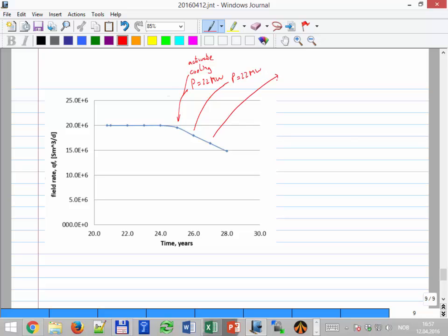And then at this point I had to reduce the rate for the temperature to be exactly equal to 150 degrees C, the temperature at the discharge. From that point it also becomes limited. The power is less than 22 megawatts, but the discharge temperature is already locked at 150. So that's why it's so important to foresee if I can make a better cooler, if the cooler can operate more efficiently to take it down closer to 6, because then I will be able to produce more. Instead of having to reduce the rate, I could produce more because I still have compression power to use.